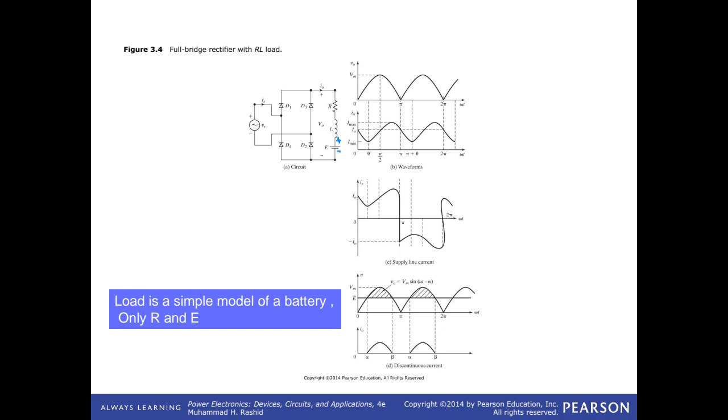So the diode D1 and diode D2, for the continuous case, always start conducting, and that is the waveform we get as the output current waveform. But as far as the discontinuous current waveform and supply, by the way, supply current is positive for the positive half and negative for the negative half, and it's very bad. You can see that it's not sinusoidal, but it is alternating current.